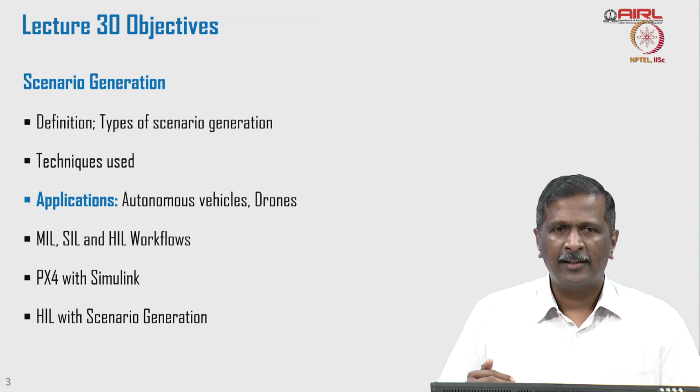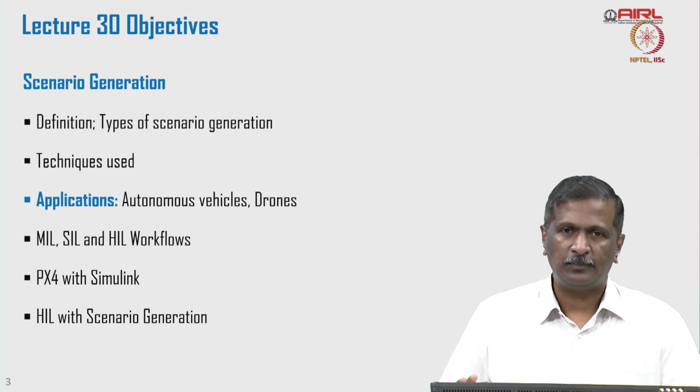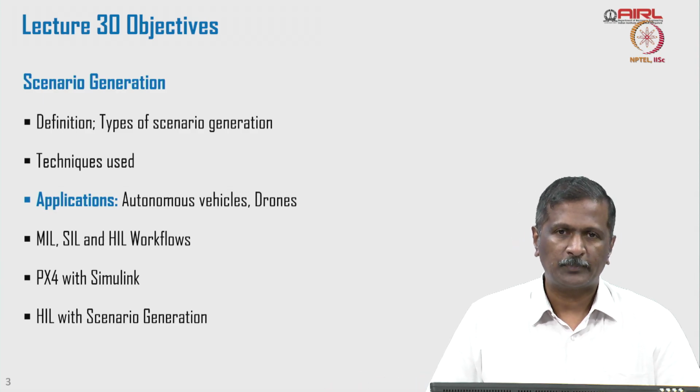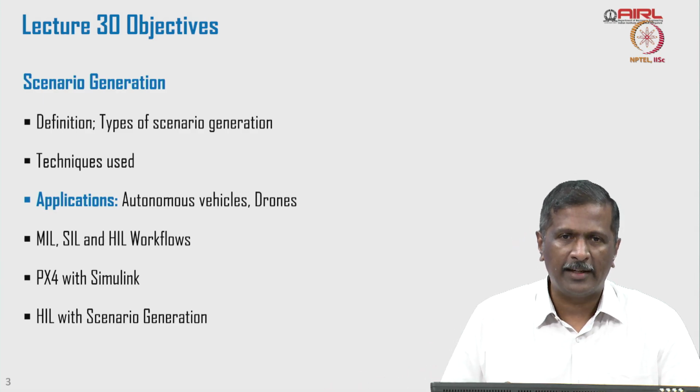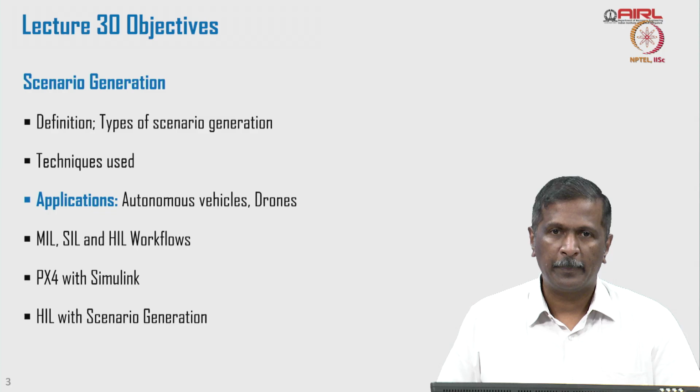How do we simulate it with Simulink? That's very important, because at the end of the day, control is going to happen in the flight controller, right? So we need to simulate so that in software in the loop we can verify. We'll also talk about hardware in the loop with the scenario generation.